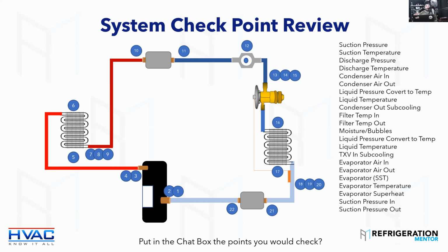This one here hasn't caused any issues with temperature drop across it, but I hear your point that maybe they should be taken out after the system's cleaned. Yeah, if you're not going to go back, then you want to take it out. If you're going back and you're going to monitor it and it's a site that you have, okay, just monitor it, because you know there is a cost to that. And there's a good question in there.